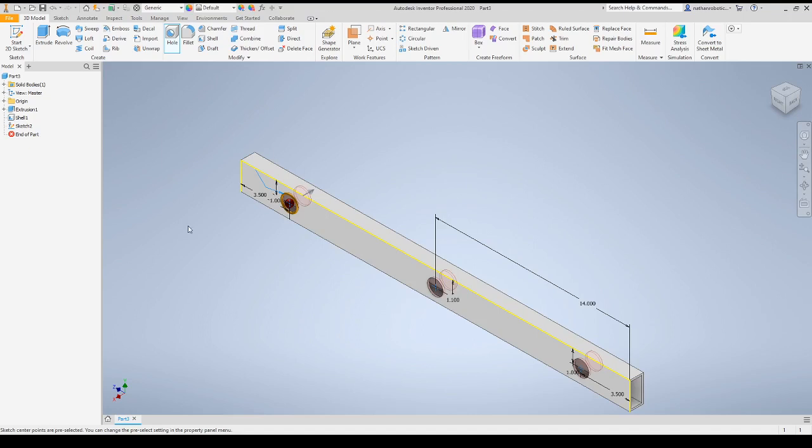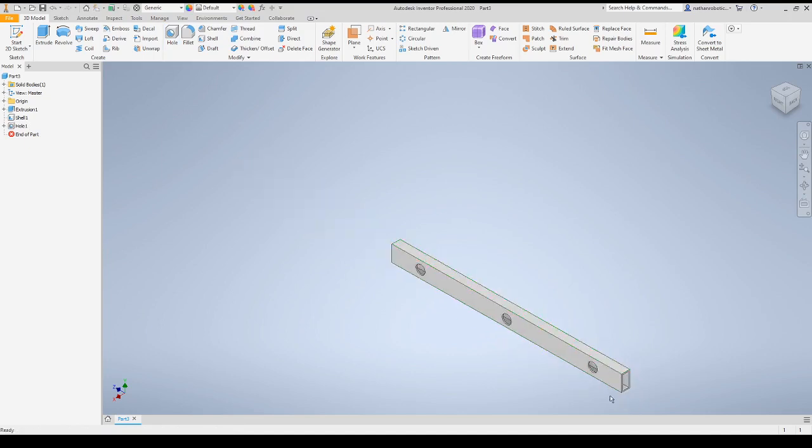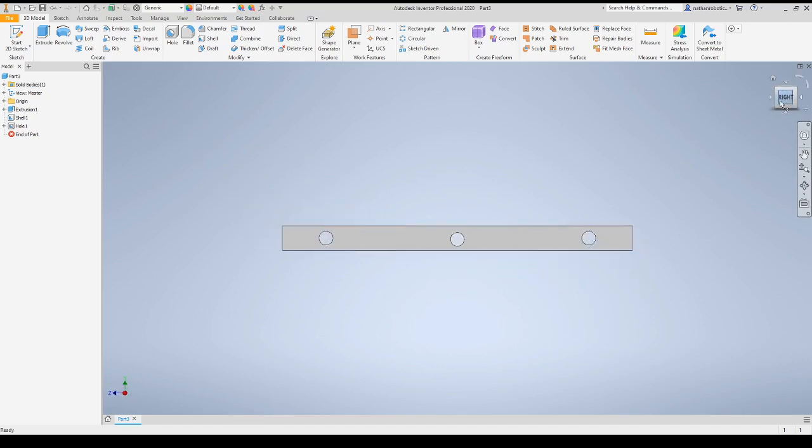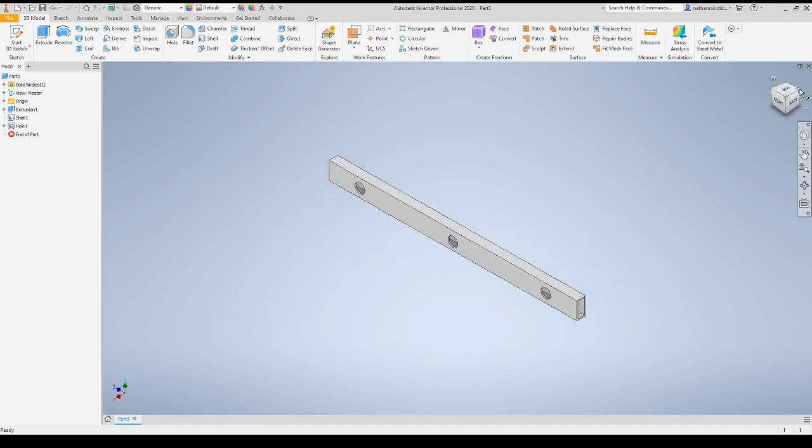And then right here, we want our dimension. It's already there, but we want it to be 1.125, because that is the size of a bearing. Depending on your machining process, you might want to size these out a little bit, like 1.127. I'm sticking with 1.125. That's what I like to do in CAD. I regret it sometimes when I get undersized holes back from manufacturers, but that's how it goes. And so, that's your basic drive rail. Pretty simple. Thank you. I'll see you in the next part.